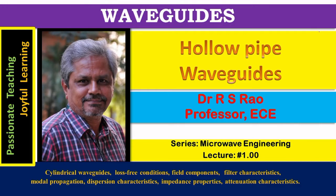Waveguides, hollow pipe waveguides, series on microwave engineering, lecture number 1.00. Hollow pipe waveguides are capable of carrying high frequency waves or signals from one point to another point without radiation losses. They carry the wave in non-TEM form.